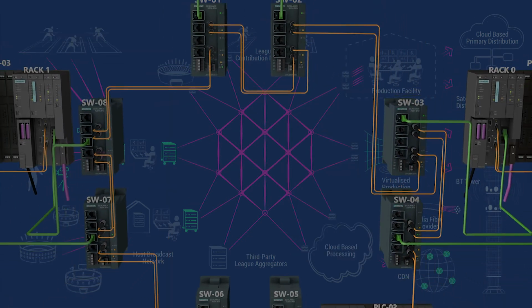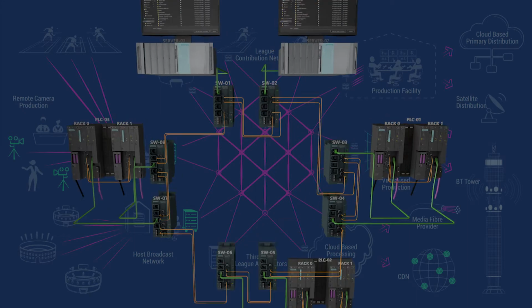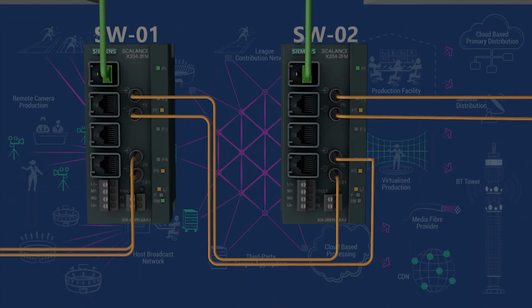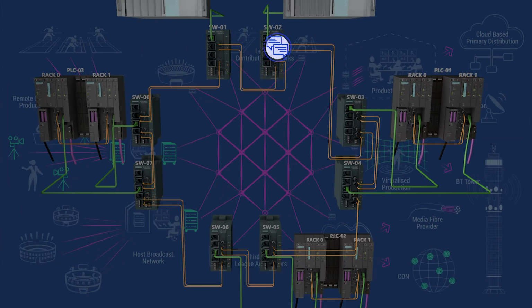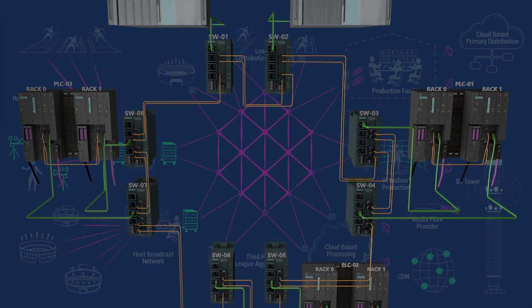In a ring network, there are two paths of communication. It means that a network switch has the ability to communicate with port 5 in one direction and port 6 in the other direction. The redundancy manager sends test messages on both ring ports. As long as the test messages reach the other ring port in each case, the redundancy manager does not consider the ring to be defective.